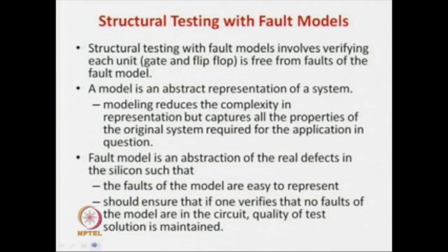So, till now we have seen that functional testing is difficult because of the exponential number of test patterns, and structural testing is beneficial because it gives a very small number of test patterns, k patterns, which is much less than 2 to the power n, yet the accuracy is very high, as large as 99.9% plus. But the problem is the huge number of pinouts, and also there can be a large number of internal 2:1 multiplexers and registers. By using registers we can save a lot of pins, but the number of registers was still the problem.